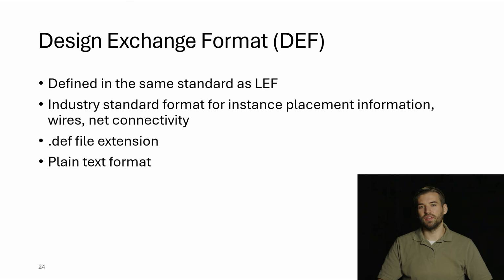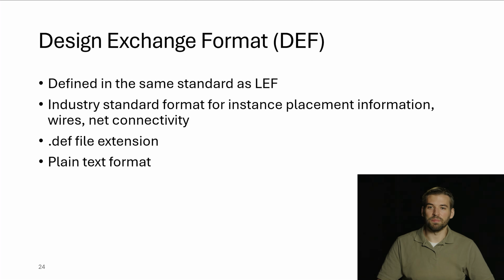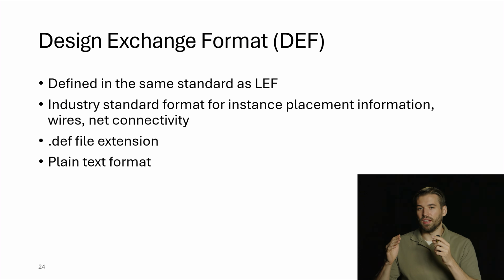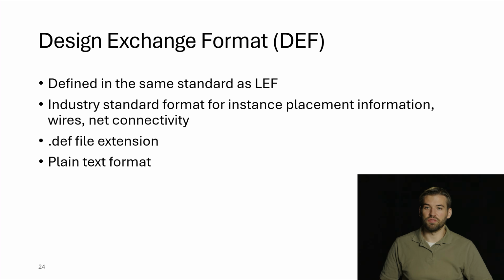Next, we have the design exchange format, or DEF. This is defined in the same standard as LEF, so it's literally the same manual if you go to look it up online. And similarly, this is an industry standard format for the instance placement information, as well as wires and net connectivity. So in the LEF format, we had all the general information for the process.